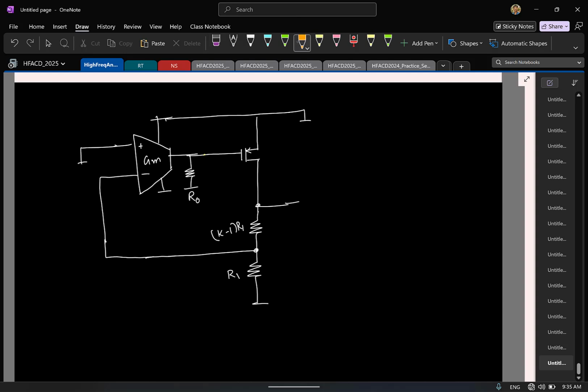Yeah, Miller. So that is one straightforward thing. You can put a Miller cap here. And sometimes in LDOs, what is also done is the following. See, in Miller compensation, the idea is you put this cap. This sort of behaves like a larger cap at low frequencies here. So effectively you have put a large cap here, correct?